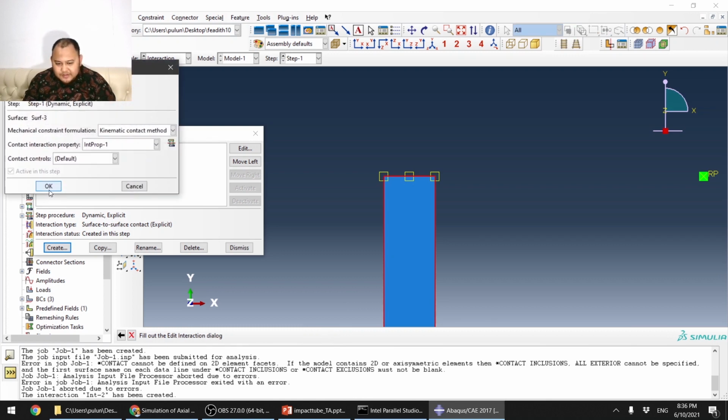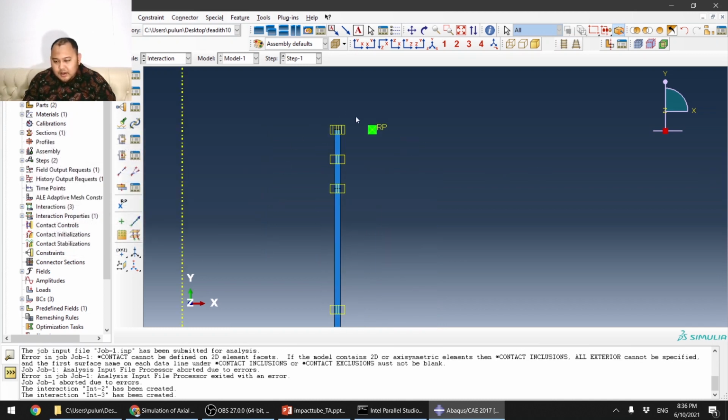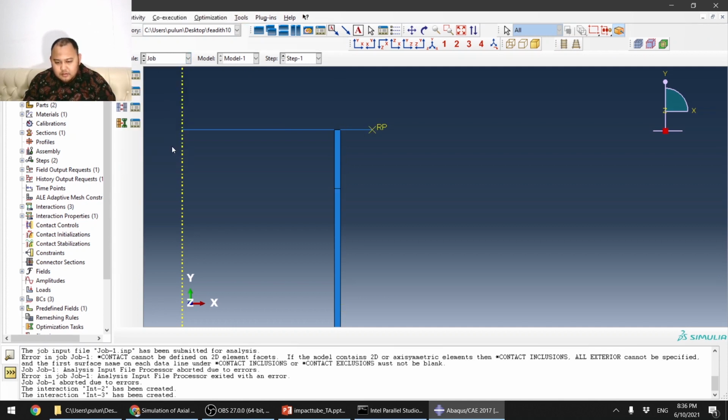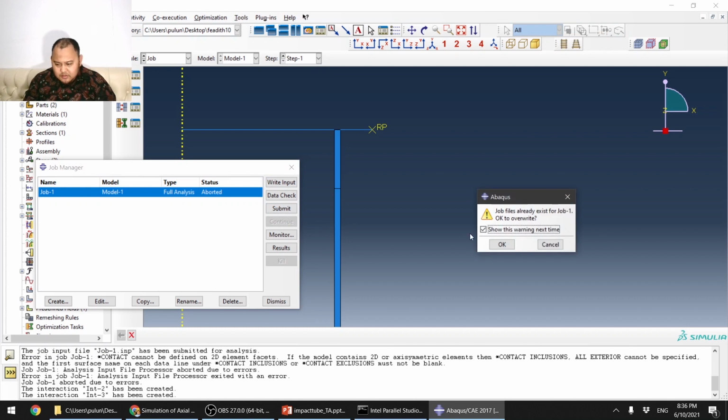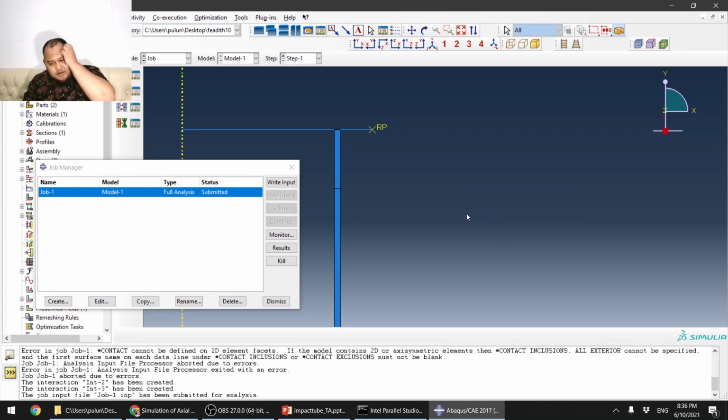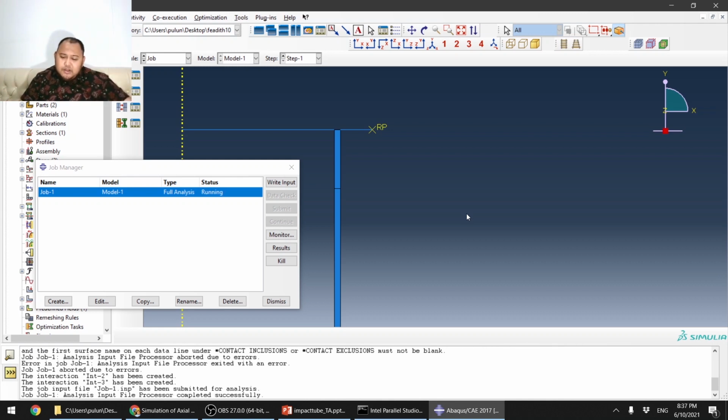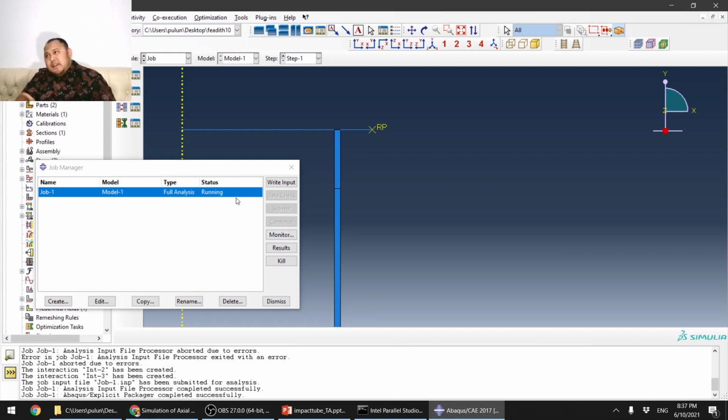Yeah, you need to do it manually. I don't know why. Do you understand why you need to specify manually? Maybe the Abaqus developers forgot to implement general contact for the 2D facets. So if you use 2D, they just give you this warning error, and you need to do it manually. The error message that we just saw.